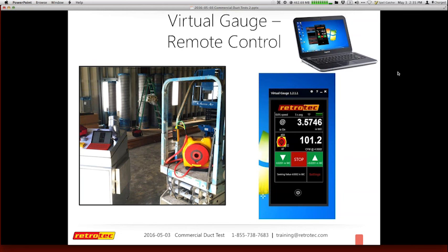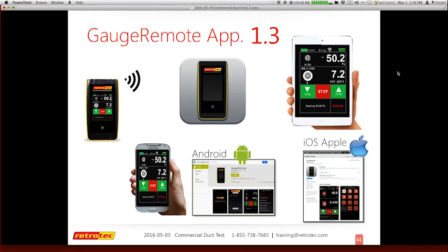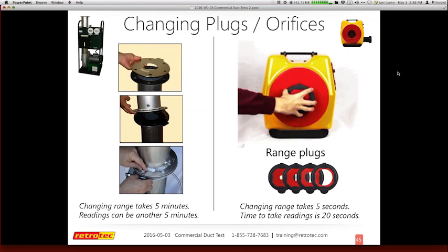For the European group, there are European units, CFM per square foot. There's also liters squared per meter squared, and again, additional units based upon your region. There's also CFM per 1,000 square feet, and we're back to CFM per 100 square feet. As you see on the left, these are all of your optional units that you could use to confirm immediate compliance. CFM alone may have you thinking you need to do a calculation based on the amount of duct you're testing, but the gauge can do all that automatically and give you the results instantly inside the gauge.